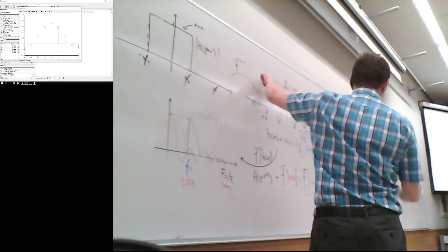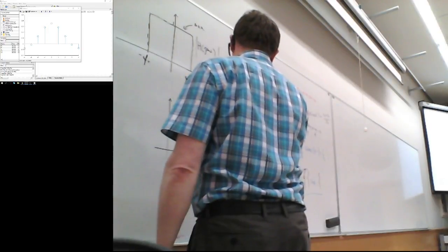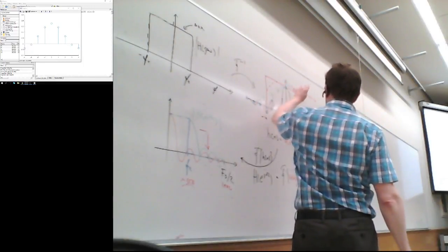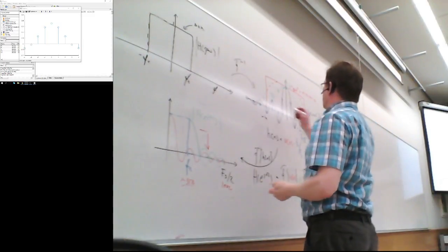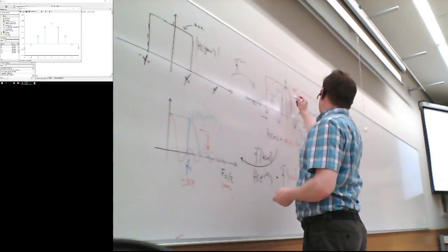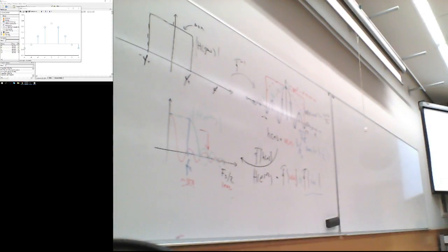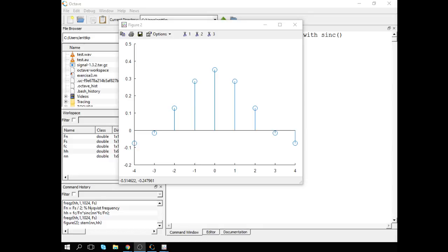So basically the only way to start getting better attenuation in the stop band is to smooth the window somehow. Get rid of these sharp edges. And one way of getting rid of the sharp edge is the triangular window, which is very simple to produce. So, just a moment. Where should I click? Here. Good. So triangular window actually goes something like this.